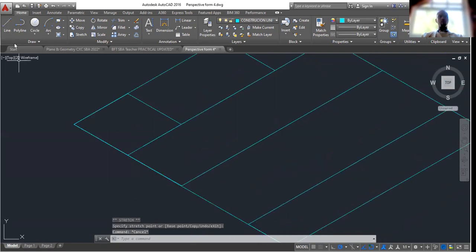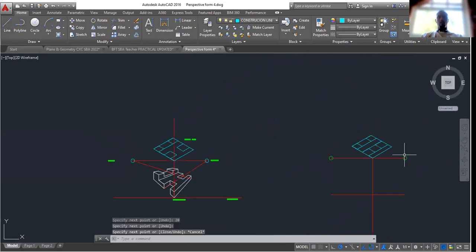Okay, and just make sure everything is in line. Okay. So now I can do my 20 millimeters going this way, 20. Then I come down until I see my X, enter, press enter again. From here, 20 millimeters. Then I come down to complete. Okay, so now we are done with our object.